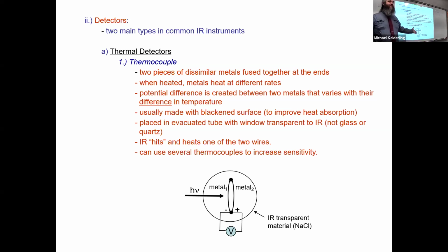Thermocouples are used as thermometers all the time. Most electronic thermometers, your probes, are thermocouples. It's one of the simplest ways to do an electronic thermometer. It's pretty reliable. It's fast responding. The other ways you can use, like a thermistor or other things, need more power. Thermocouples are very common. They also can be quite small, which is good for a probe thermometer.